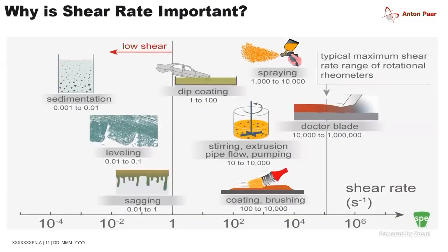And the reason why viscosity is important, as I said, is that if you're dealing with something that has structure, it depends on what your conditions are. For instance, if I'm interested in looking at sedimentation or how stable the material is, I focus more at low shear rate conditions. So thinking of sedimentation and leveling impacts, those are at very low shear rate conditions. But if I'm looking at, say, extrusion or stirring, these are at extremely high shear rate conditions.